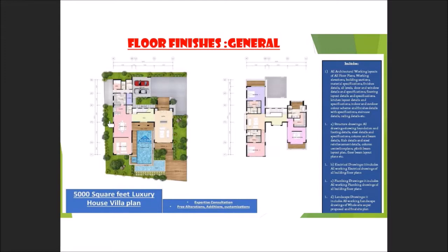Let's say you see this one in pink color. This is the dining area, for example. If I zoom in, dining area, pink color, this one may be homogeneous tiles. Family room, this one may be parquet. And hall area may be ceramic tiles. So the architect highlights different colors just to make sure that people understand this area has a different specification. Even if you have a different color, consider it a different specification.